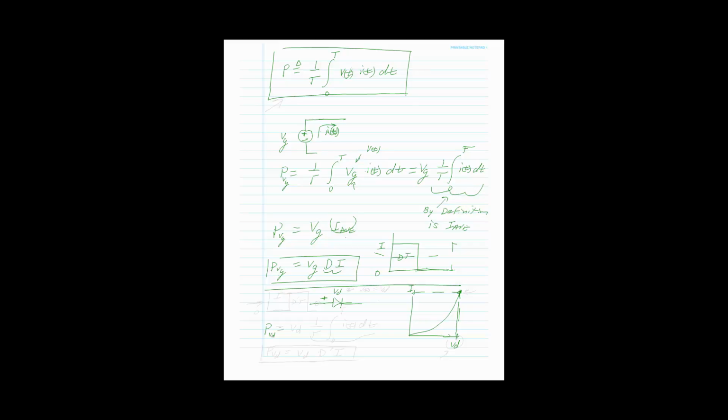Again, the same equation. You go back to here. What's V of T? V of T is fixed, fixed by the diode current. If you're supplying 20 amps, then you look at 20 amps and find in the spec what the forward drop is. So again, I can pull that out of the integral.